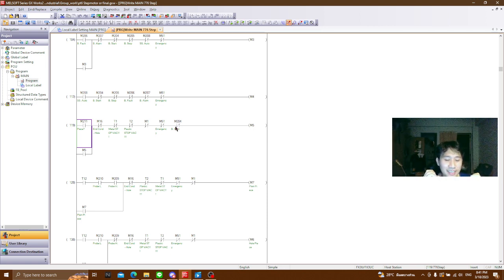How do we check that there is a workpiece in the cylinder on the slicer? We have a sensor for checking the workpiece, which is M211. We are also facing this: if we have worked on one workpiece, the slicer will push out, and then it will activate again, because the sensor also detects the cylinder of the slicer. So we will create it like this one. I will explain this briefly after this. We have to reset the value of it after the work cycle is done.